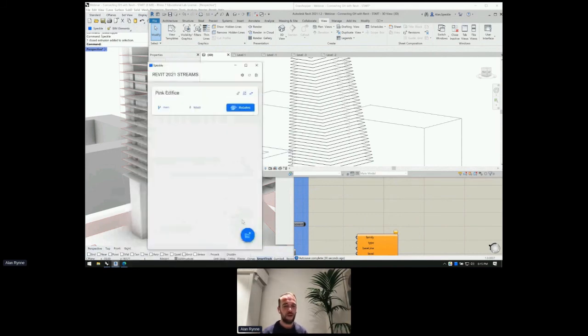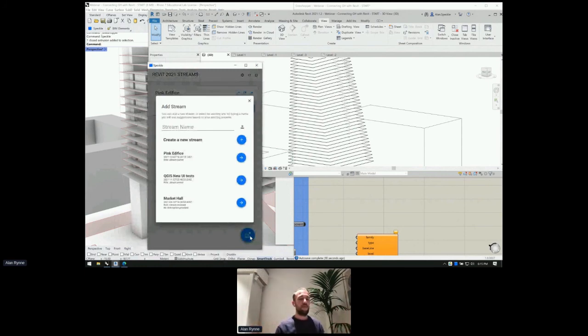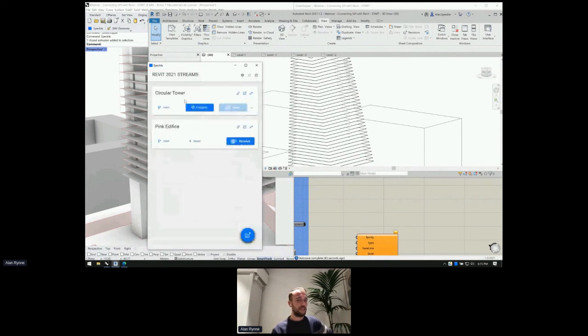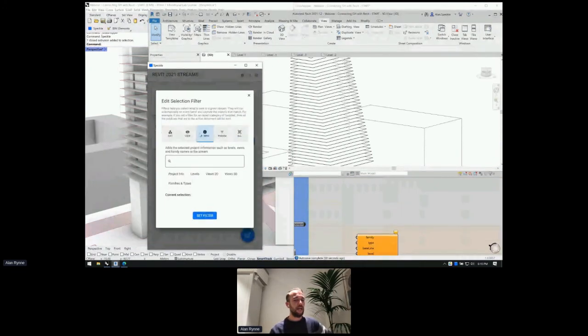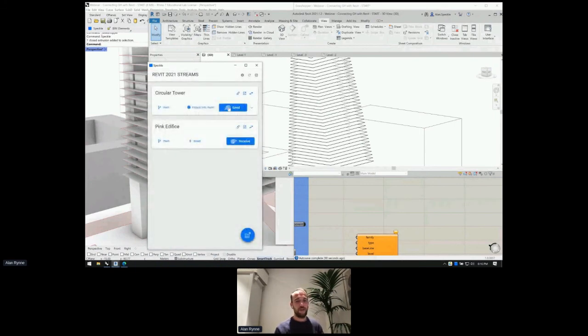Well, for that, I'm going to create a new stream. You could create a branch instance stream, but I'm not going to get into that. Just going to randomly create a new stream in my Revit project, which is now called Circle Tower. Okay, perfect. And in this case, instead of selecting objects to send, I'm going to use the set edit objects filter option. In this filter option, we have some property info values, some filters that we can select. In this case, what we want is to send all of the proper project information: if it has an origin, constructor, whatever information is attached to this specific project, the available levels, if we have them or not. In this case, it's not interesting because we are generating them from Grasshopper. But what is interesting is to send the families and types to be able to accurately pinpoint what is available in the project that I'm going to send this geometry to. So we can set this filter and send.